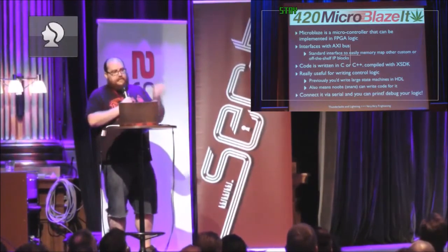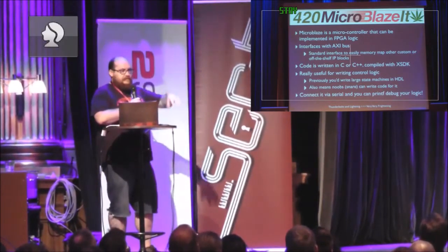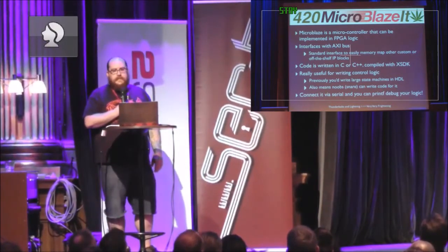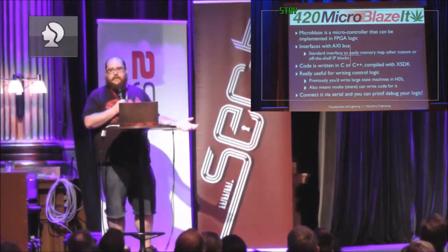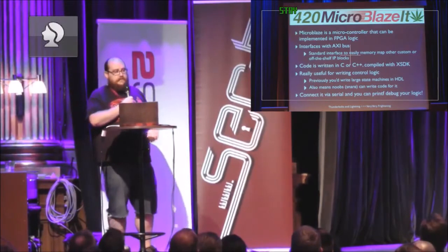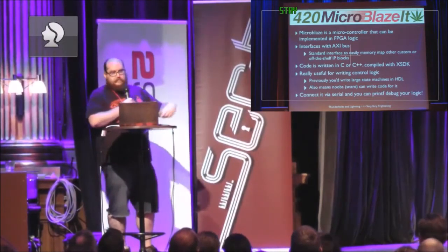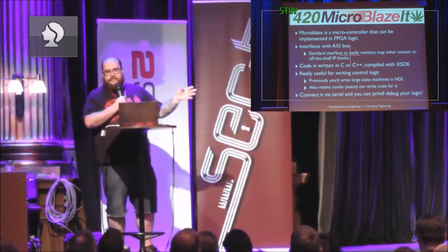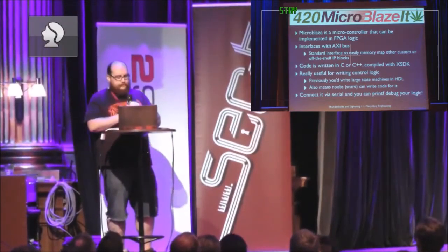So one of the other neat features is that we've got a UART on the development board, and can communicate with the MicroBlaze code via serial. So I wrote a little text UI thing, and we can just connect to it via serial and send some commands, and our code then tells the PCI Express block what to do. Great.